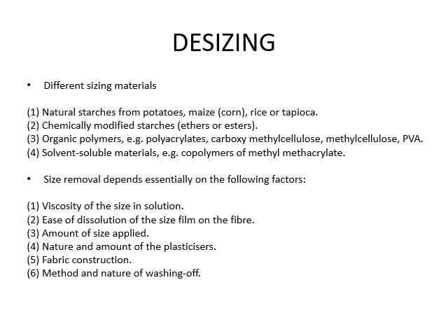So an appropriate washing-off process has to be there. And the last point is the temperature of washing-off. Some sizes require a particular temperature for removal from the fabric, and some sizes get removed easily even at room temperature washing. So accordingly we have to select the temperature of the washing-off process.